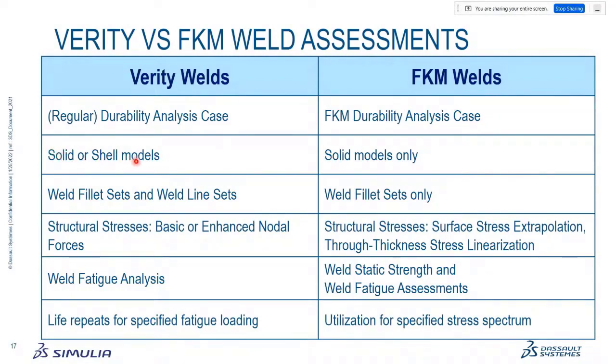With Verity, we currently support solid and shell models, while we currently only support solid models for FKM. With Verity, you can model the fillet itself, or you can play more tricks if you want using the weld line sets. With FKM today, we only support that you have to define the weld fillet sets.